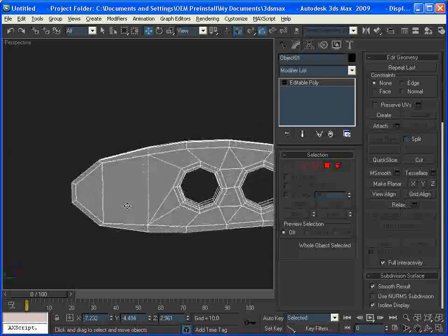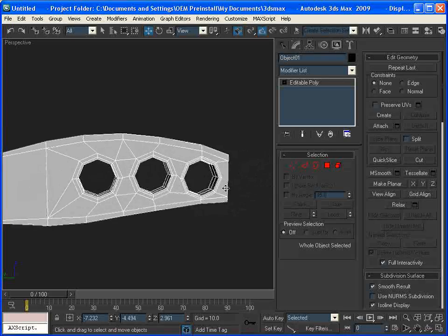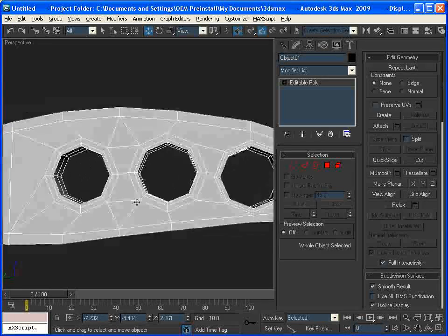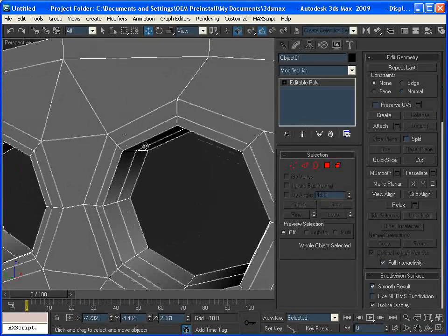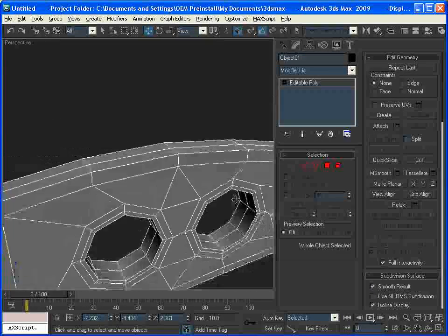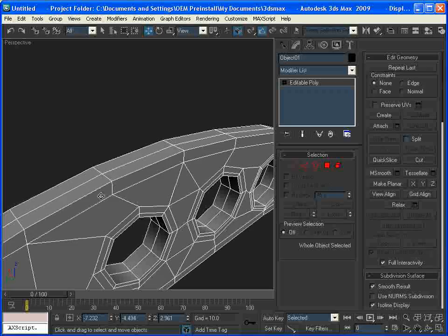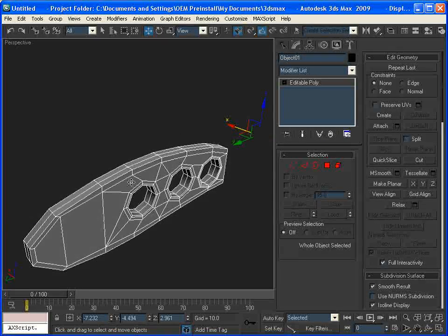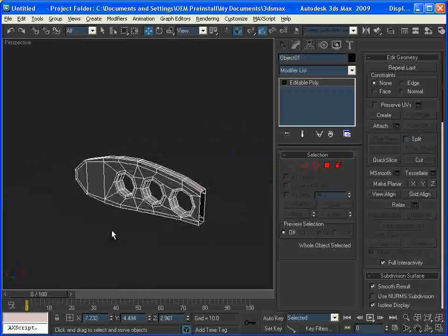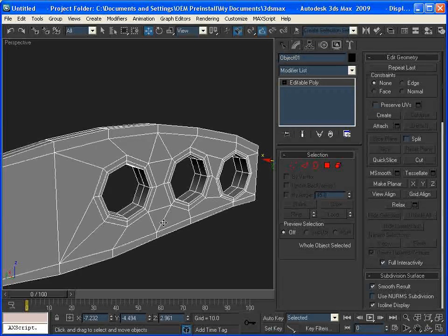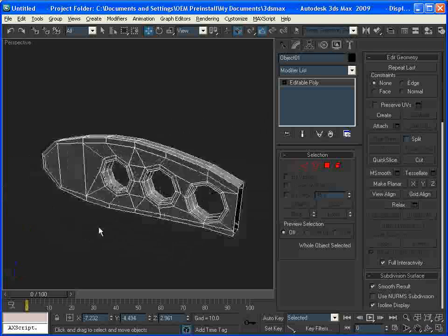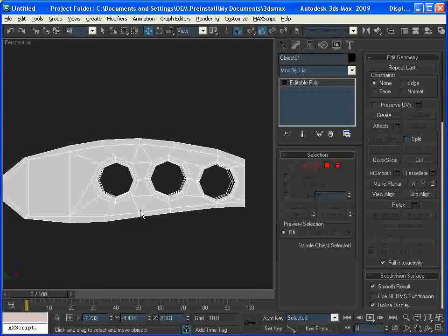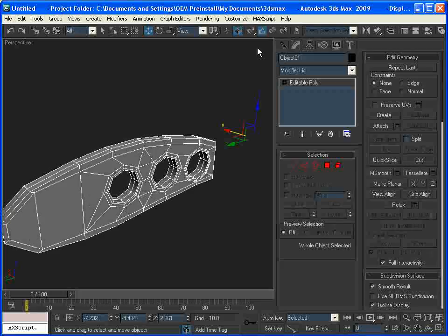This should subdivide well by looking at things. This whole area is messy, but again, each circle is insulated from everything else by these two supporting edges here, and the edges are insulated from the circles and all this mess by the supporting edge. So the edges won't be hurt, the circles won't be hurt. So basically it's all set. We're going to have an absolute mess in this area, but it doesn't matter at all because all of the edges that we can actually see changing, everything that actually has a change in contour, is totally protected or insulated from everything else.